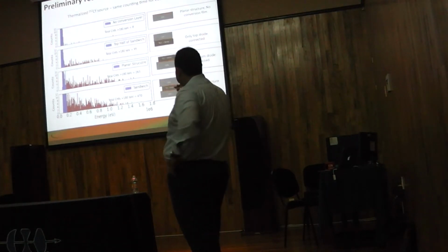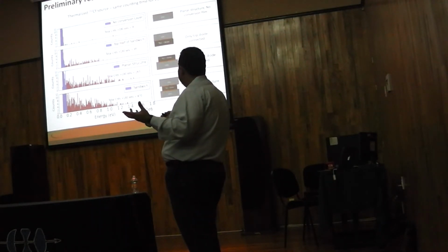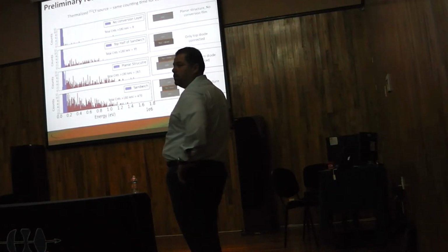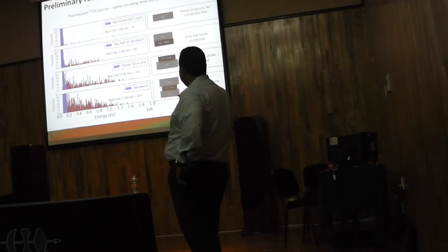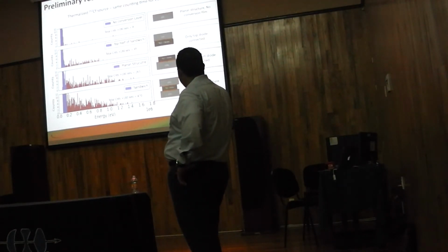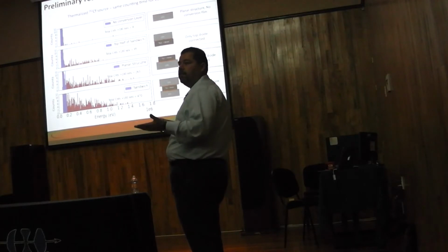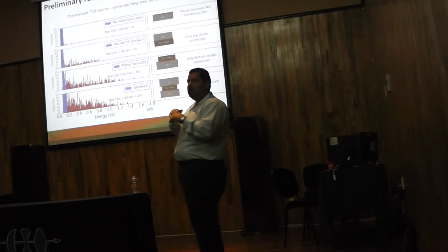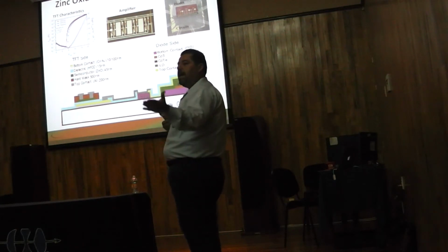So this is actually data that we took from a californium-252 radioactive neutron source that we had at UT Dallas. So we have basically the diode with no conversion layer. We don't have any counts. Then we put only the converting layer on the top, we get about 95 counts. We put it on the bottom, we get 265 or 263 counts. Then we do the sandwich approach, and we get 470 counts. So it does help to have the sandwich approach, and this is with actual neutrons striking on the sensor. So it does prove that this process works. But it's only half of the equation.